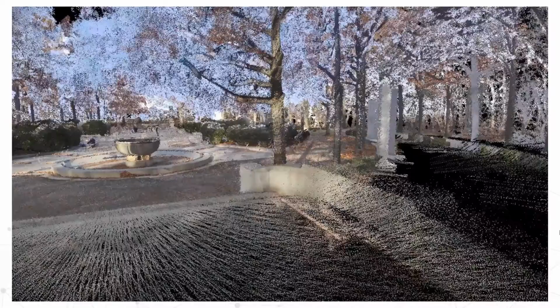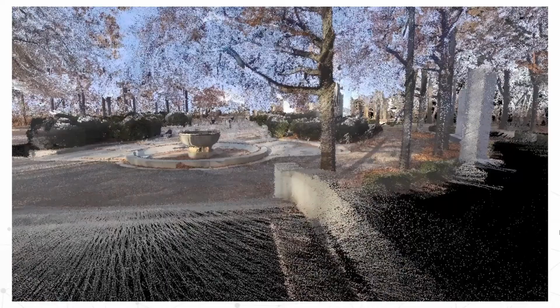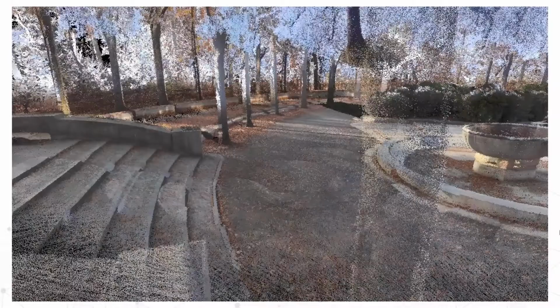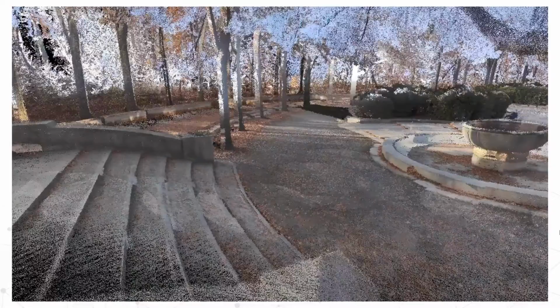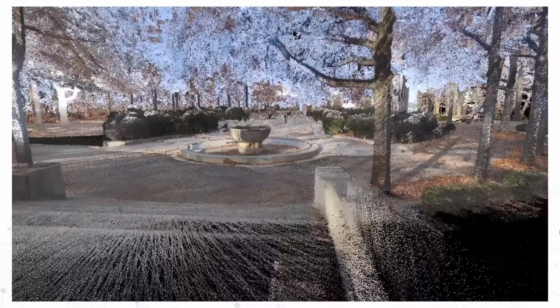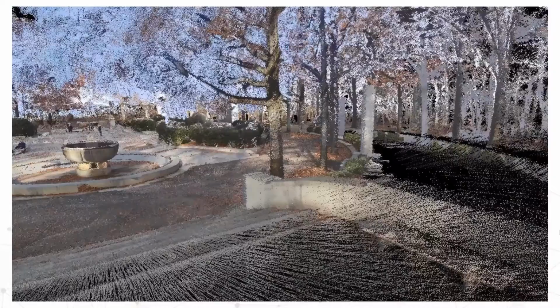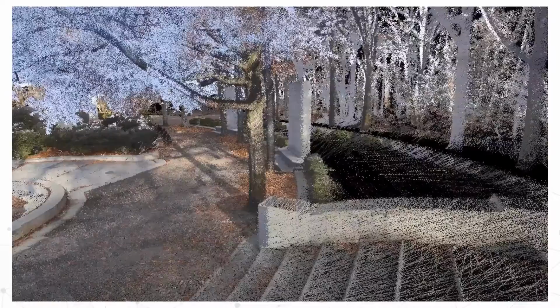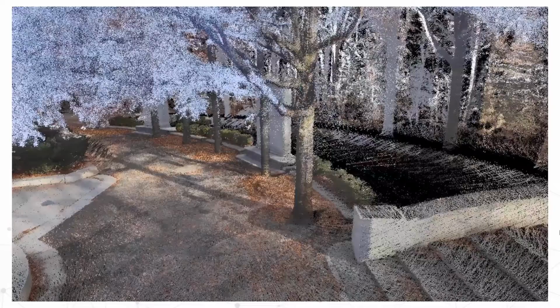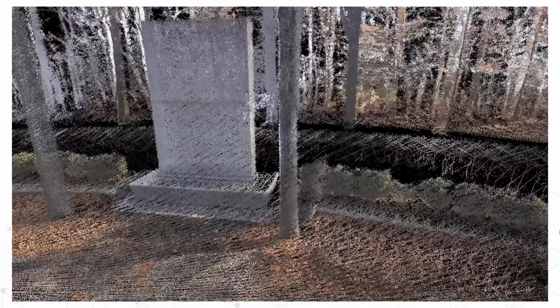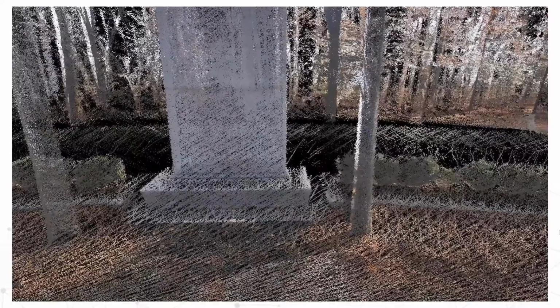Just one thing to have in mind with Discovery is that the Horizon is mounted at the back, and you're not able to paint the buildings as you would be used to when you are doing handheld capture. To be able to capture the top structures of the buildings, one needs to keep a distance from them to have a good scan angle to reach the top parts.